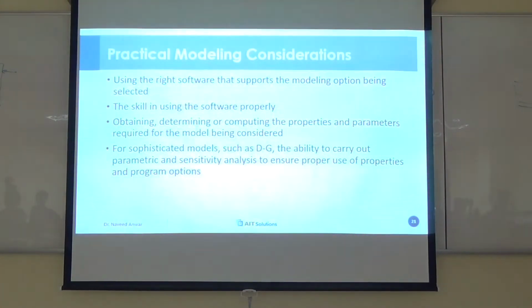That means you can say, this is my bearing. Actually, it converts that into a link element. So you can specify the dimension of the bearing, and it becomes a link element in the model. But you can say, I want a diaphragm here, I want a pier here, I want an abutment here. So it has all the bridge terminology. Internally, they are converted into finite elements, and SAP is used.